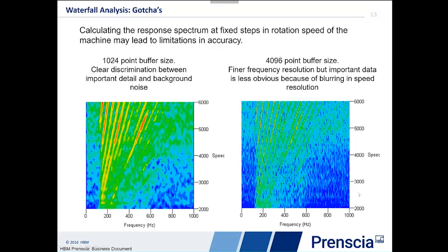So if you consider a very large buffer, it'll cover a range of speed. The speed can't be assumed to be constant throughout this buffer because it's very large, and therefore, instead of having one peak at a specific frequency, this peak will be smeared, and you'll have a wider peak, right? Because the frequencies are swept because the buffer is too large.